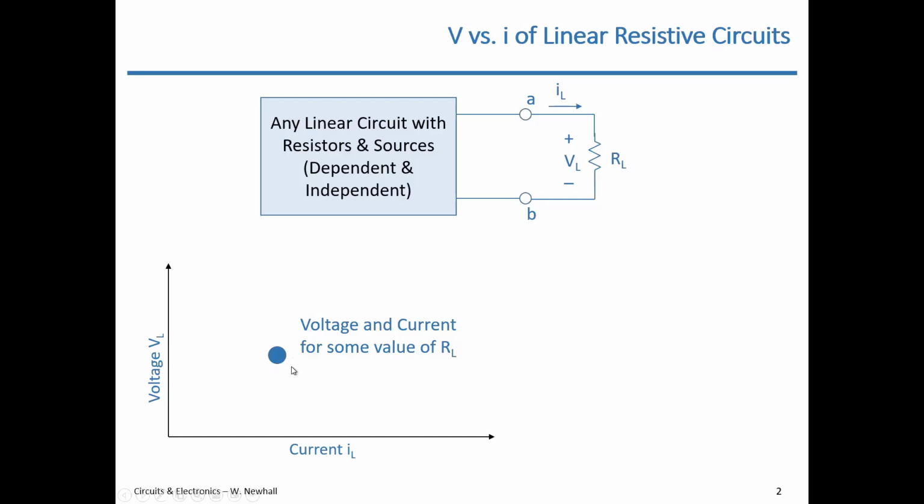If I take that resistance value all the way to infinity, that's like an open circuit, I'm going to have no current flowing, right? If I have an open circuit, R equals infinity, I have no current flowing. So I sub L equals 0 amps when R sub L is infinity. That's an open circuit. Infinite resistance is called an open circuit.